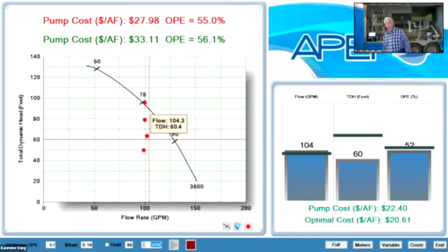have the investment. And if we get a wet winter and the water levels come up, it'll slow the pump back down and save you energy. So it's a little bigger investment up front, but it's very costly to pull pumps in and out all the time.